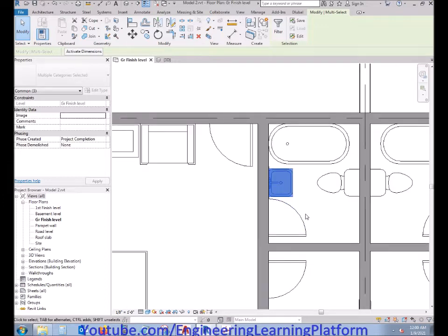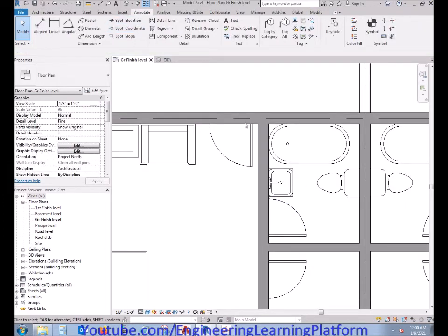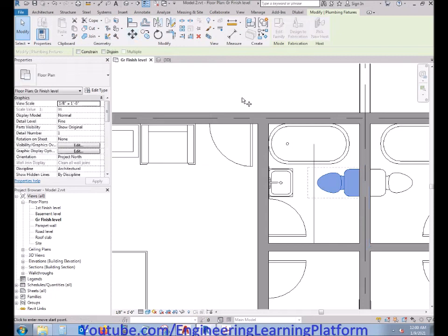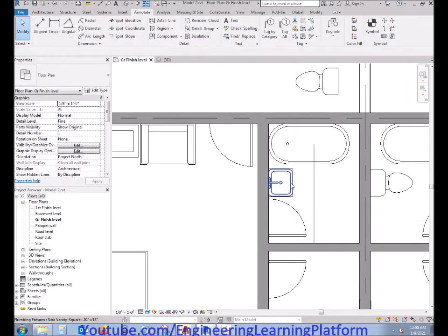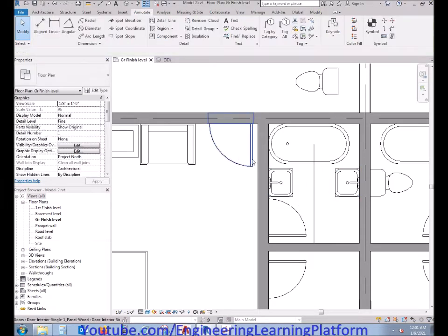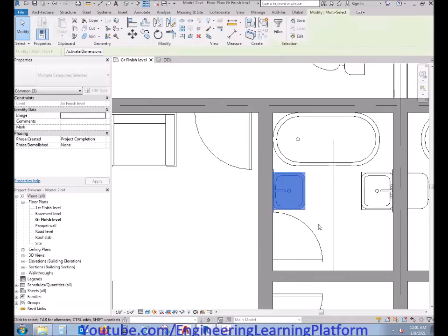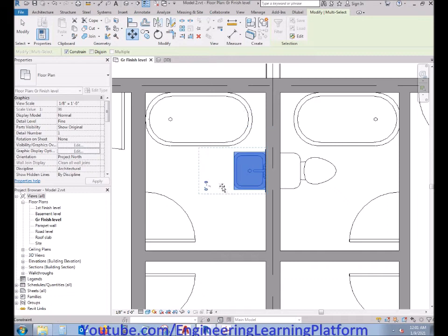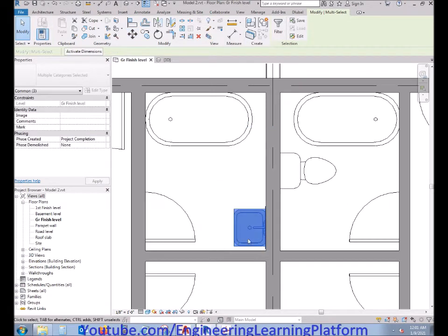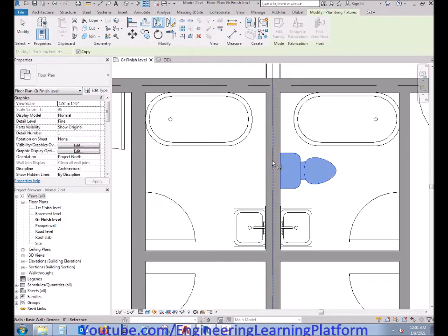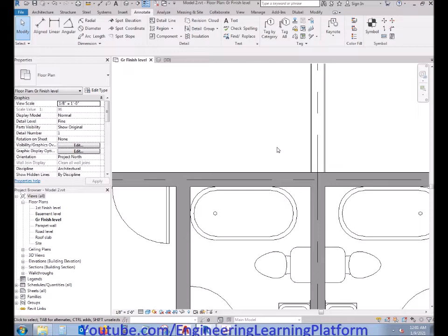So over here I'll have to add it on the wall just in front of the door. But first I'll have to remove the commode to make space for the mirror to be attached to the wall, as the mirror can't be placed in the model unless attached to a wall. So I have to temporarily remove the commode to bring the basin on this wall. Now it is done. I can mirror it and similarly mirror the commode and delete the additional one.